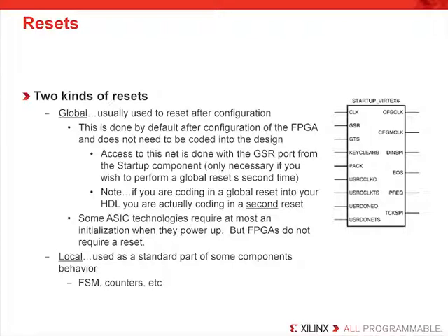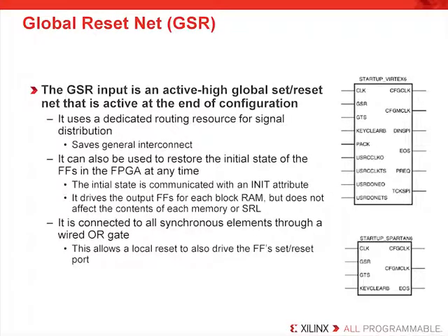Local resets can be built at your discretion, although Xilinx recommends that they be synchronous and managed by the designer to minimize the number of control signals you have in your overall design. It should not be necessary for you to use the GSR to build a global reset. It is actually discouraged due to its slow performance.